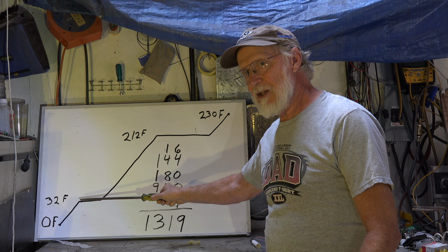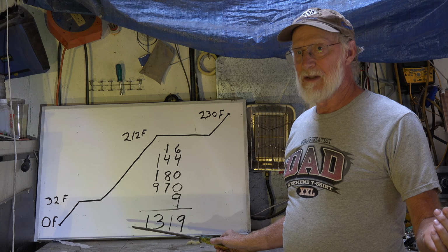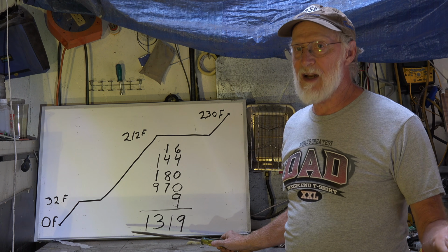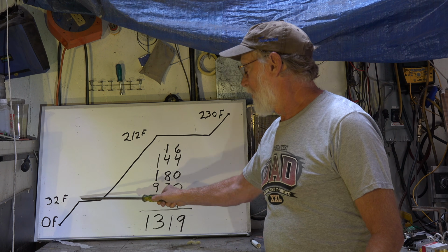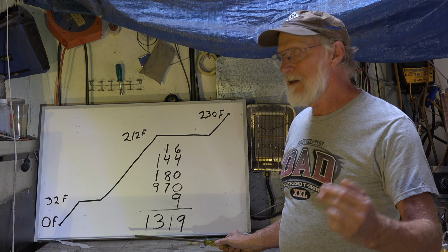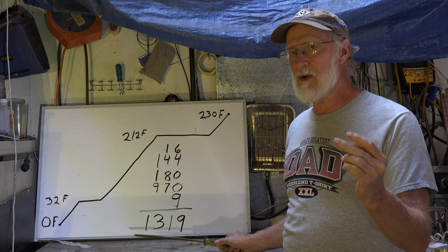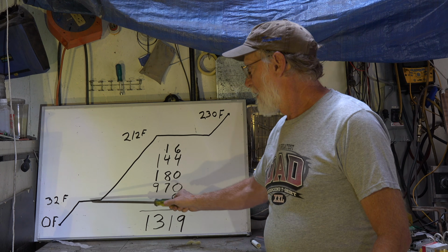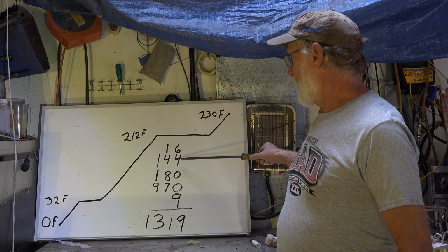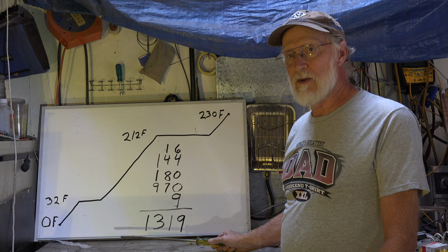When it reaches 32 degrees, it can no longer be ice. To get to 33 degrees, it's got to be water. So, flat line here is absorbing latent heat at 144 BTUs per pound. Okay, that number's right there, 144 BTUs. We have now got water at 32 degrees.